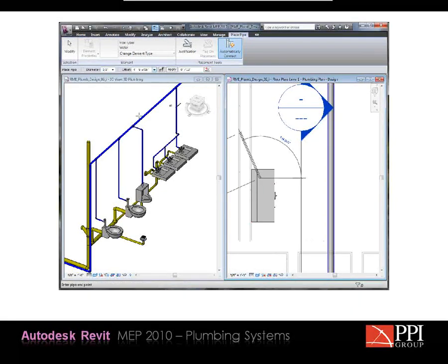So by starting from the connector, we're going to define an elevation that we want it to go to from the connector, and a 1 inch pipe diameter to start from. Offset at 4 feet. Going to come out just about 2.5 feet. And then we're going to come across and run to 10 feet and connect into our main cold water line. There we go.